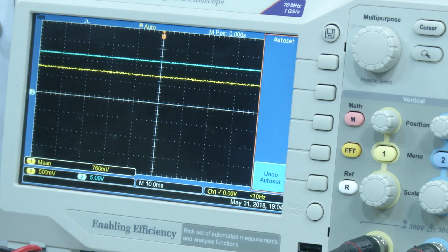That is the cut-in voltage of our diode. When I take a diode, it will always be at cut-in voltage, which means it does not allow the capacitor to charge more than 0.7. Since it is at 0.7, it cannot go to the negative state, and so it cannot discharge. The capacitor stays in this state until we provide a negative triggering pulse.